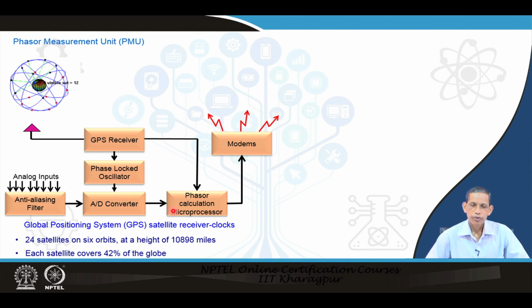The device calculates the phasors just like the relay does, rather more accurately, and we will talk about that. And then the corresponding phasors are provided with the time information, called time tagging, and then this is fed to the network in the system to the next destination, where the data are used for different applications through any communication medium, in particular dedicated fiber optic or so.